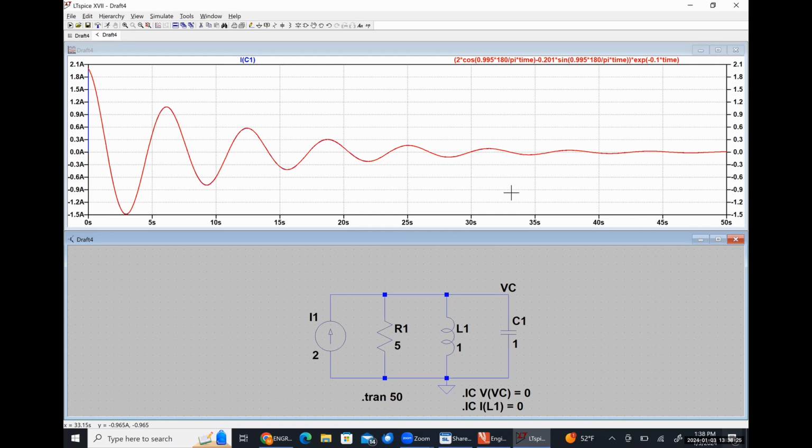So typing in the expression as we solved for it gave us a problem, and it's because we weren't considering how LTspice interprets things, right? LTspice, as I mentioned previously, expresses all angles in degrees, and it does nodal analysis effectively. So we have to keep both of those pieces of information in the back of our mind when putting in our mathematical expressions if we want things to come out correct.